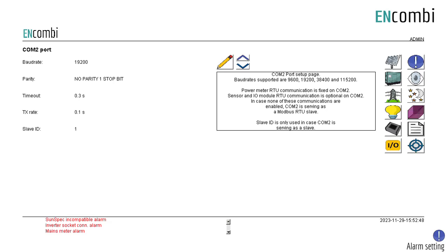There are different types of alarm settings available in EC Web. You have to set your alarms by going to Alarm Setting. And the status of alarms will appear in the left side corner of EC Web.